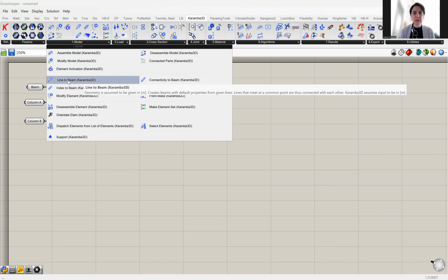Wherever you have beams or frames or trusses, you should define all the lines as beams. Wherever you have surfaces, you can refer to them as a surface and define a mesh. In this tutorial, we're going to just work with beams, and columns are a different source of beams, but they're loaded differently, so that's okay.